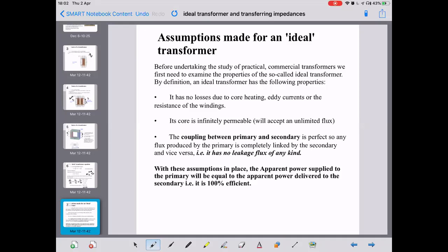So when people are designing transformers, do they always use the ideal transformer calculations, or do they assume losses? They would have to take losses into consideration, because there are losses. And what they also have to take into account is the overall system volt drops. So they'll have multiple tap-ins on the transformer, so they can pick a tap-in with a slightly different number of turns to get the ideal setup when it's in place. So that's kind of more important, really. But they would have to consider what the losses were going to be, through heating of the core and so on. I'm not an expert, Lewis. I've never designed a transformer, so I don't really know what goes into it. But like anything else, when you get down to that fine detail, there's a lot more to it than when you simplify it.